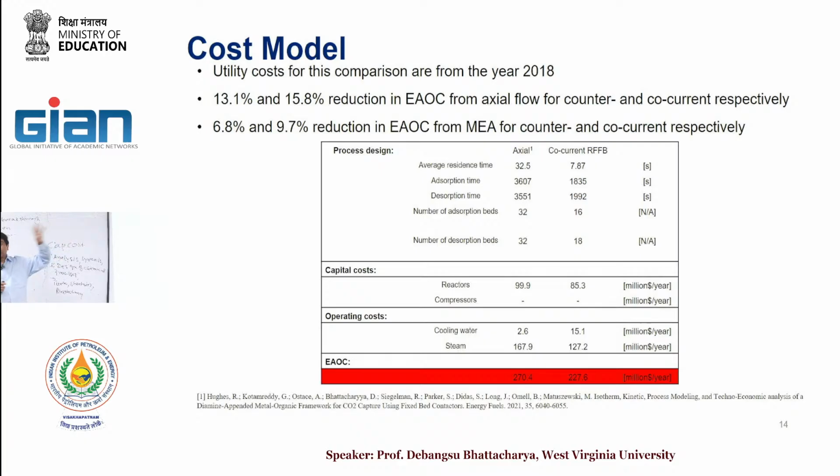So that's one advantage, and then the steam cost also goes down. You see that instead of counter current, the co-current was optimal. I'm not showing the results here for all of those, but we have a paper that you can compare. This is an interesting concept without doing any fancy stuff. If you have the vessel, put it into 2 annulus form, and then you can have a radial flow configuration. Okay?